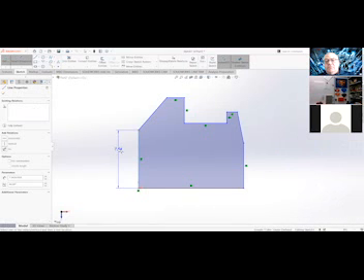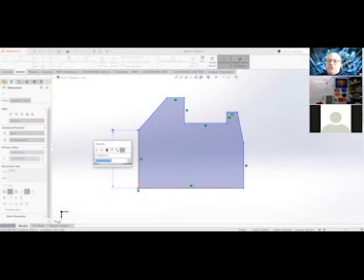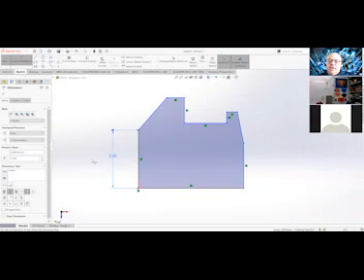I can just pick a line. It knows where the endpoints are. It's built into the program. So this one's showing 7.5, basically. Well, it's not what I want. But once I left click again, so left click to pick the line, left click to place the dimension, now it's going to let me change it. So I can type in 2.5. Now you just hit enter. And the whole drawing's scale perception changes so that this line is now 2.5 and the proportioning has stayed the same. It's a pretty amazing tool.